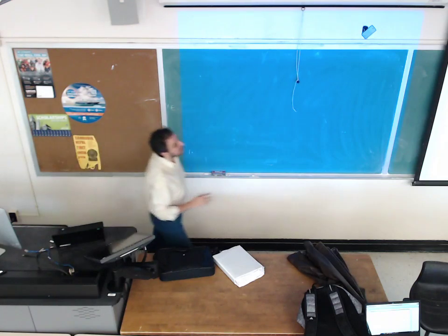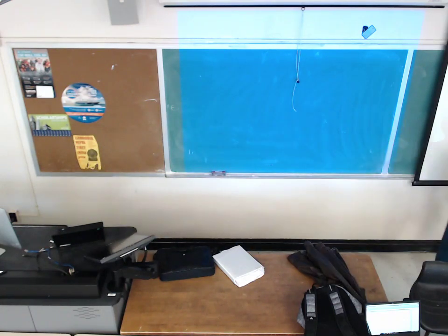For some standard forms of the mass, I have the I in this table. So if you have a single point mass, just a concentrated mass, which is rotating about the center with the distance of r, this point mass is rotating about this, and the distance is r. I for this is going to be m, whatever is the mass, times r squared.